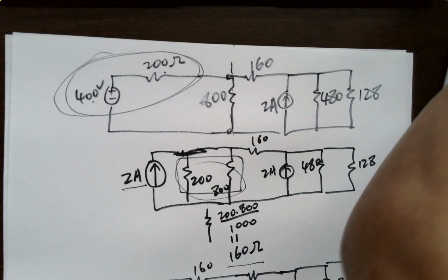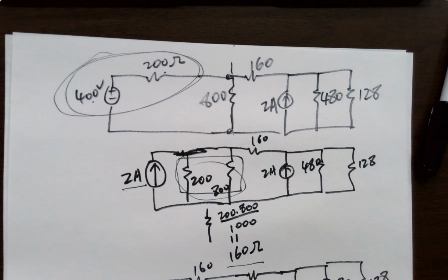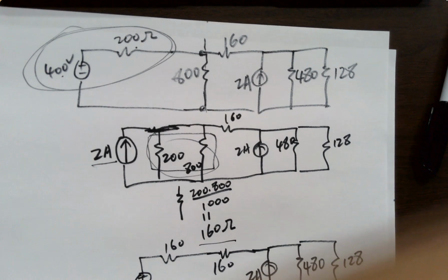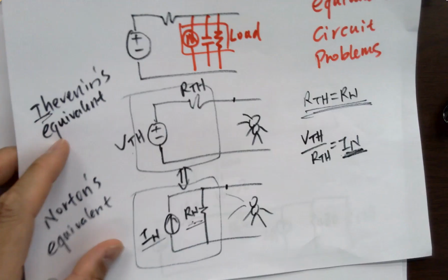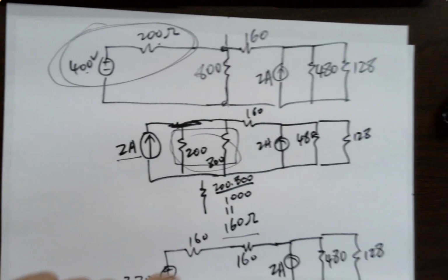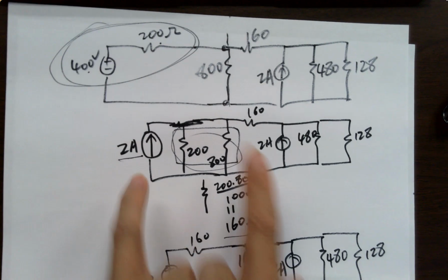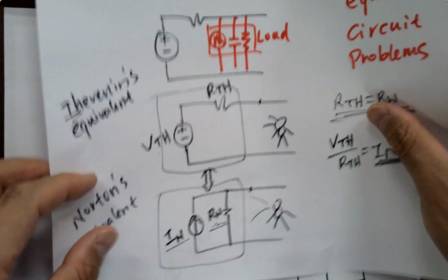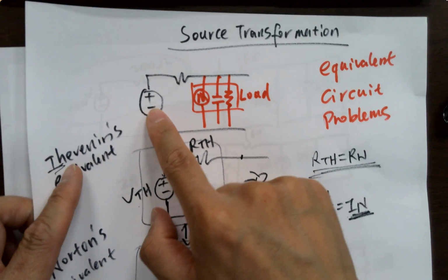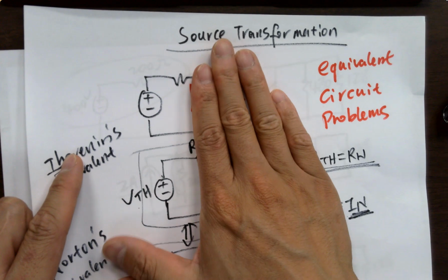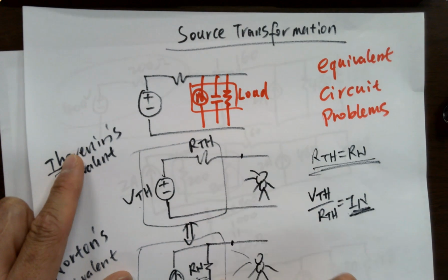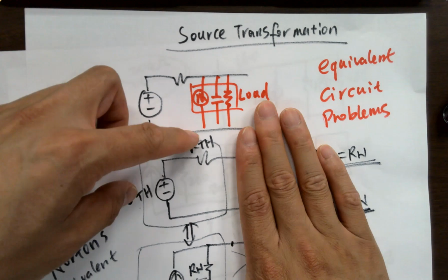Thanks for stopping me because I'm moving in the wrong direction now. It's good. So let's look at it. Whatever you said was right. But moving to here, we shouldn't move to here. We should stop here and merge these two current sources. But never mind. Let's go back. Come back here. Remember, you have one voltage source in series with one resistor, right? You can convert it to this by doing what? By doing this divided by this, Ohm's law, to get a current.